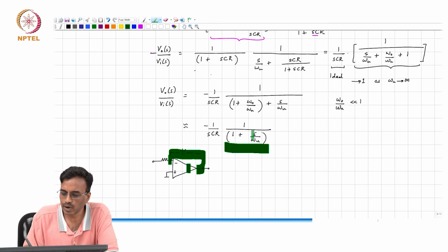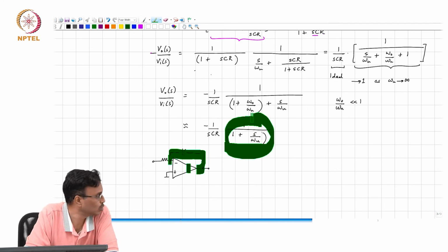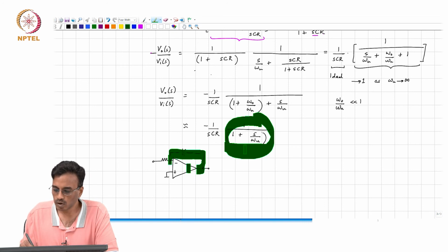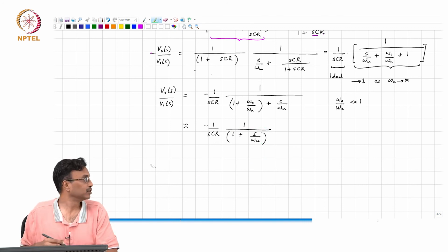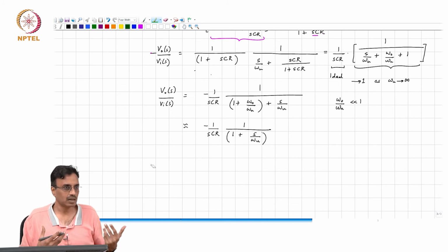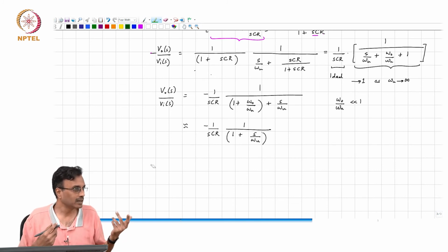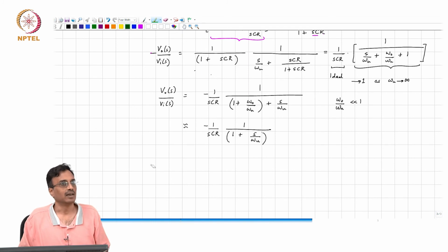It is telling us that at very, very high frequency, basically the behavior must eventually have a pole at omega u. This is clear, people, alright. So, in English what this means is that the op amp is not infinitely fast, right, it takes some time to react, and as a result, what comment can we make about the integration?